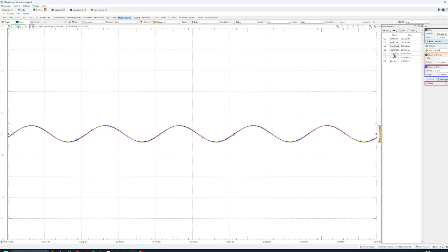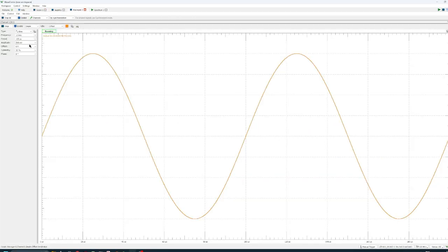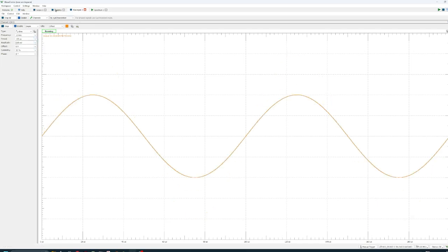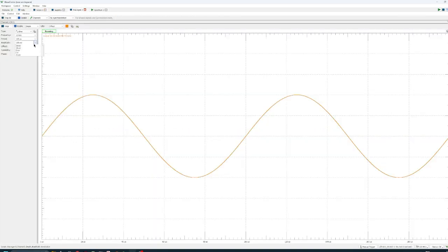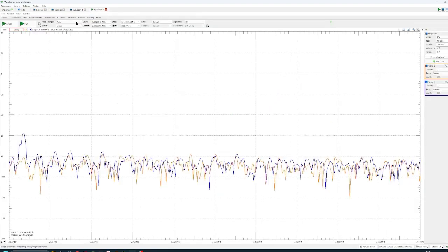Everything looks okay. Let's try one more value. Wave gen, let's just try 100. Let's do the same thing. Go to scope, and as you can see, the maximum values, peak to peak, and frequency are pretty consistent with one another, and the gain is still over 0.9. It hasn't really changed while tweaking the amplitude. It stayed pretty much the same as with 500.